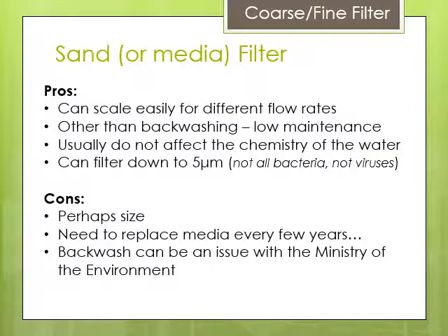So what are the pros? It scales to different flow rates. Typically sand filters, if they're sized properly, can go to just about any flow rate you want. So that's very helpful.